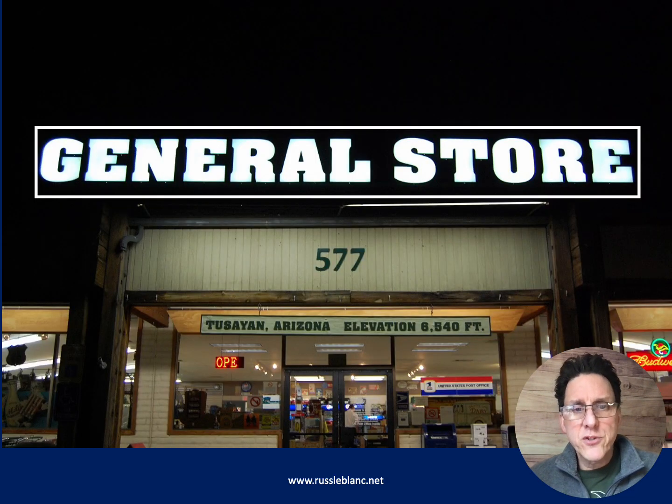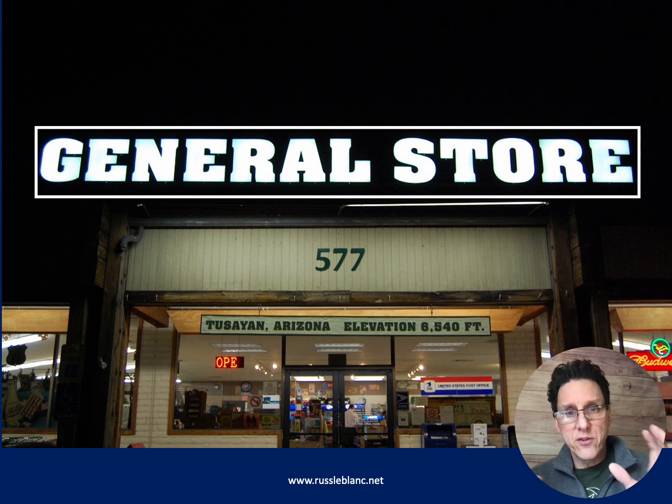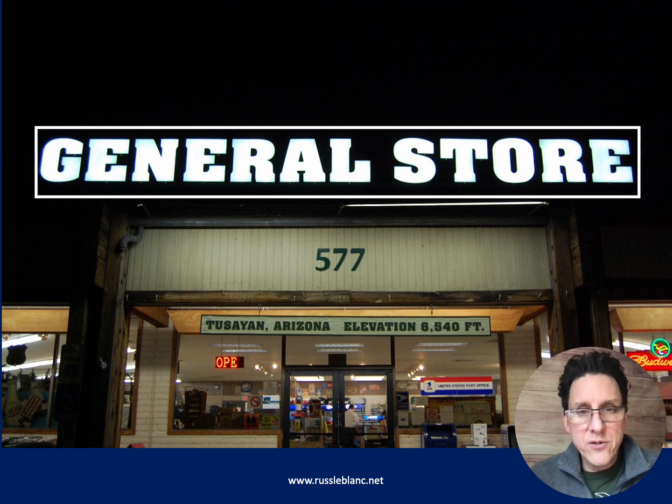Here's the general store sign. And again, this is directly above the entrance to this commercial space, right? So that's the required branch circuit, and we have the lighting outlet there, or the sign outlet, excuse me.